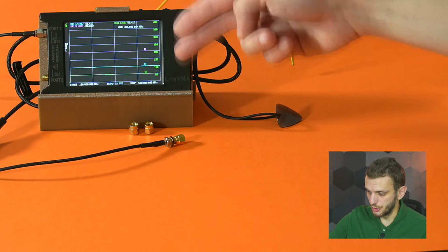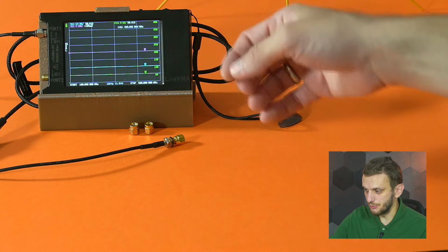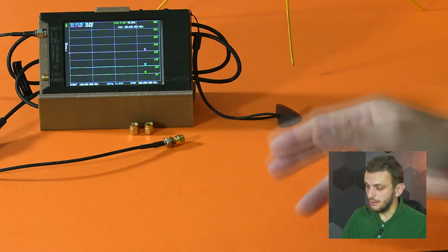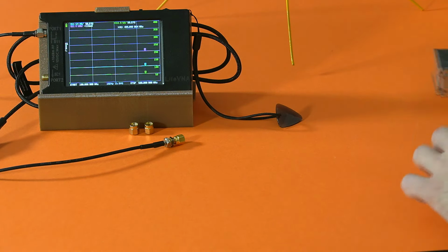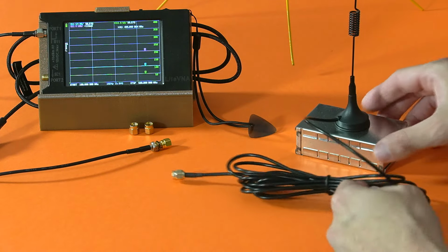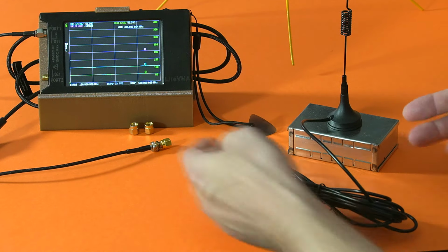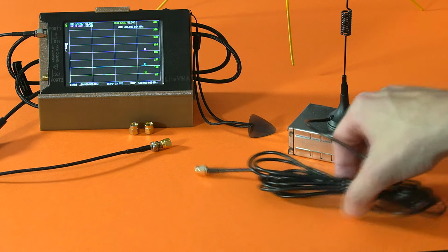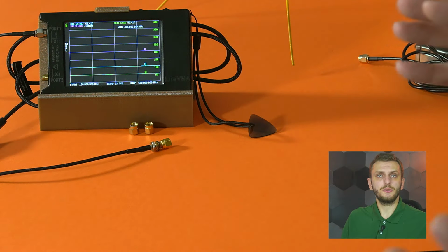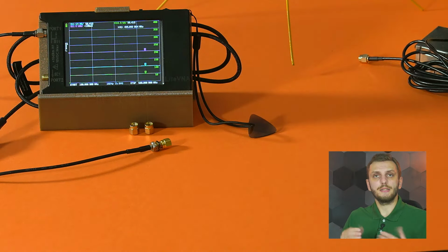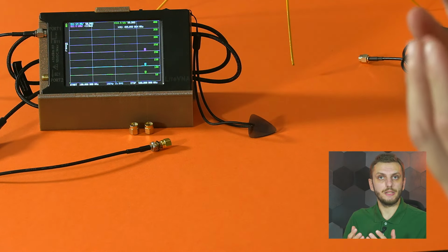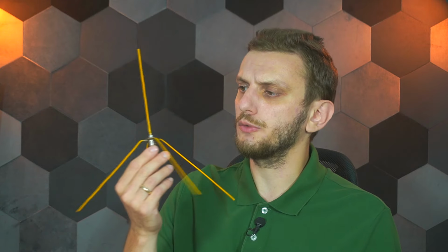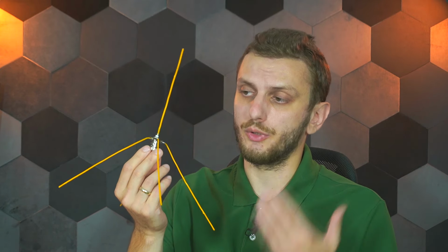So right now it's showing the 50 ohm termination resistance response, and in case the measurement point is not the same as the antenna point, for example, if there's a cable in between the actual antenna and the measurement point, this needs to be compensated for. And the other thing to keep in mind is that the antenna impedance is highly dependent on the environment around the antenna. So this is a ground plane antenna that I previously built for the 70 centimeter band.